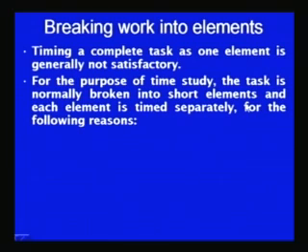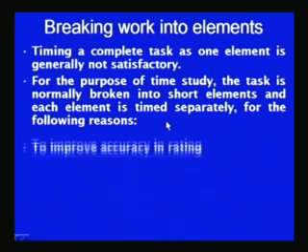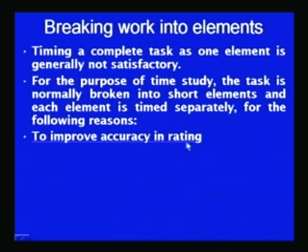That is why, for the purpose of time study, the task is broken into short elements and each element is timed separately, so that accurate rating of the worker for each element can be done, and the time for each element can be obtained accurately, so as to set the time standard as accurate as possible. It also helps to find out the high fatigue causing elements, so that steps can be taken to isolate those elements which are causing excessive fatigue, and also helps in fixing the suitable fatigue allowance for the workers who are carrying out those high fatigue causing elements.